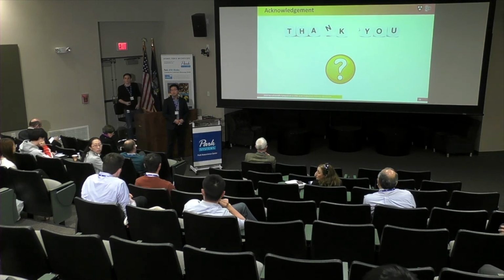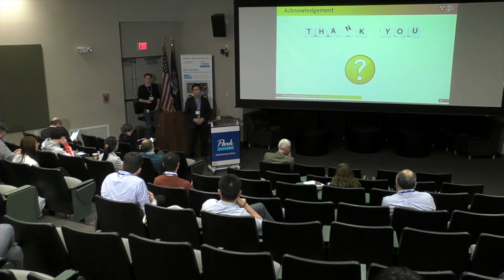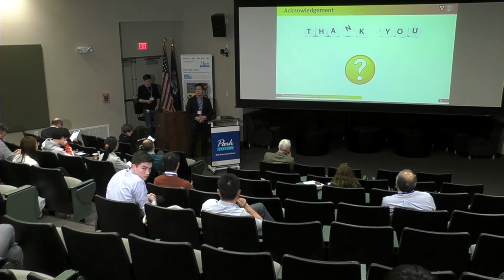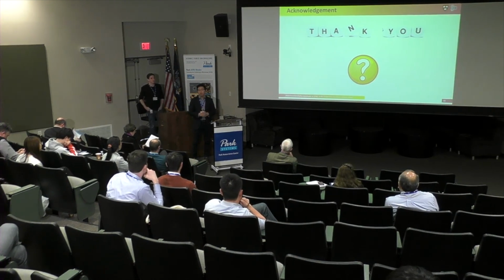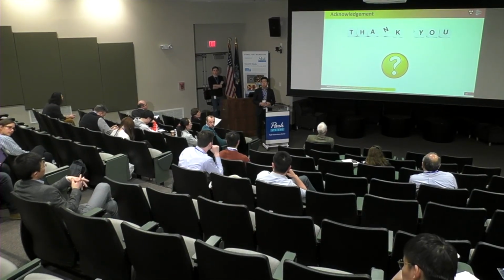Any questions? Yep. I have a question about the beam size. When you use the electron beam to pattern the straw size? Yes, that's just an extreme case if we want to make a really thin one, for example 50 nanometers in diameter or width. For the bigger ones, we can still use direct laser writing and then thin down using oxidation. So your case is you're trying to go to the extreme, trying to make it as thin and light as possible.